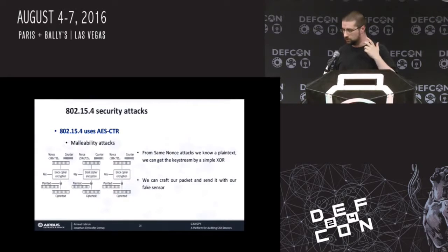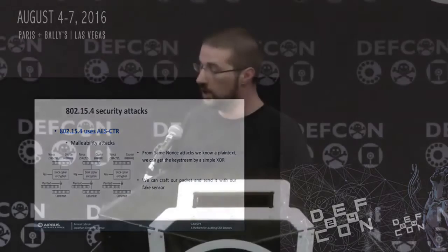Non-volatile memory. Usually when you have counters to prevent replay attacks, these counters are only kept in memory and they are never stored in non-volatile memory. That means that if you are able to reboot a device, you reset the counters and you have replay attacks. And if you have not used cryptography properly, you have both replay attacks and same-nonce attack, and then you can have malleability attack and thus forge encrypted frames without having the key.